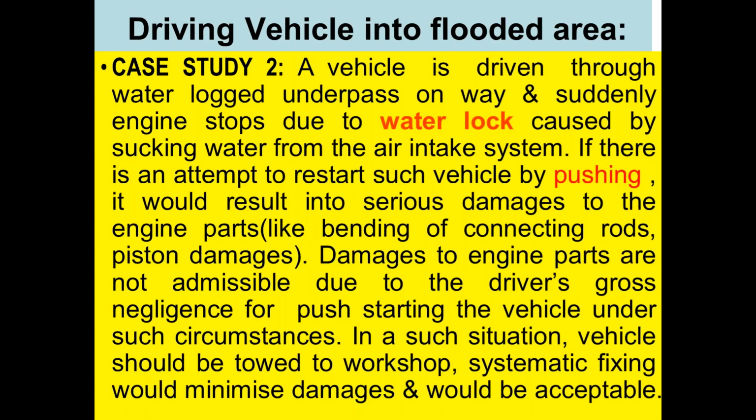Now, driving a vehicle into a flooded area. A vehicle is driven through a waterlogged underpass on the way and suddenly the engine stops due to waterlock caused by sucking water from the air intake system. If there is an attempt to restart the vehicle by pushing, it would result in serious damage to the engine parts, like bending of the connecting rod and piston damages. Damages to engine parts are not admissible due to the driver's gross negligence for push starting the engine under such circumstances. In such a situation, the vehicle should be towed to the workshop. Systematic fixing would minimize damages and would be acceptable.